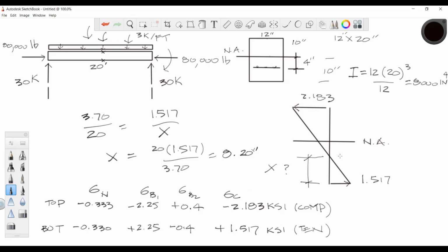This is what you would call a post-tensioned or a pre-tensioned type of pre-stressed concrete. A lot of times they use that term, pre-stressed concrete beam. These are used quite often because they can be manufactured and then just brought out on the job and put into place. So it already has that combined stress involved in it, and then when it loads, it helps overcome that.